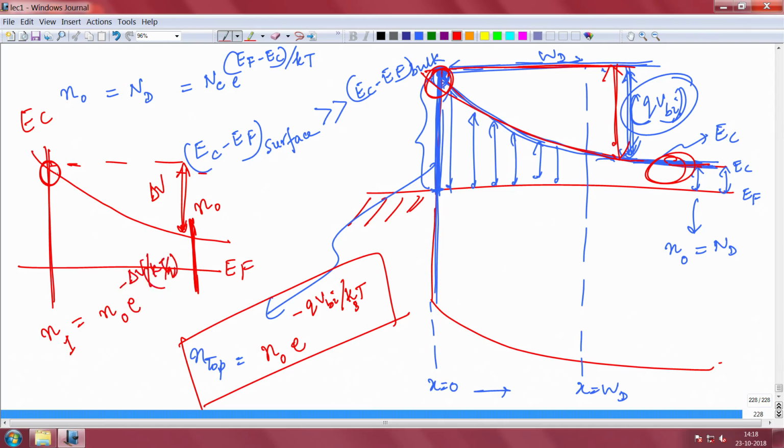That is, it goes exponentially with the variation in the energy band. So this is the extra gap delta V that has arisen here, and because the Fermi level has gotten that much farther away, the electron concentration will decrease by the exponential of that amount.